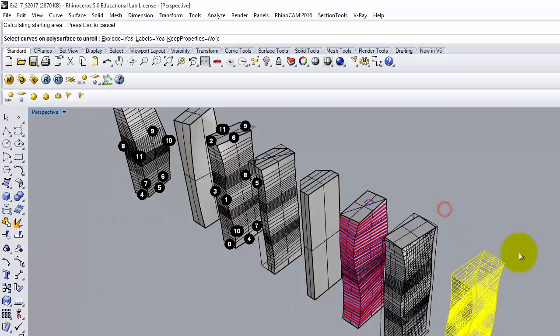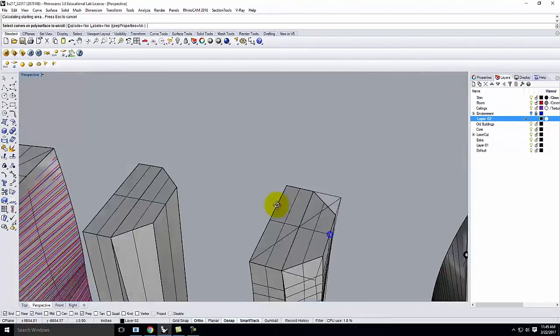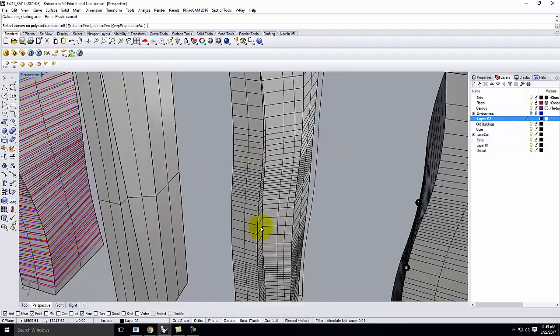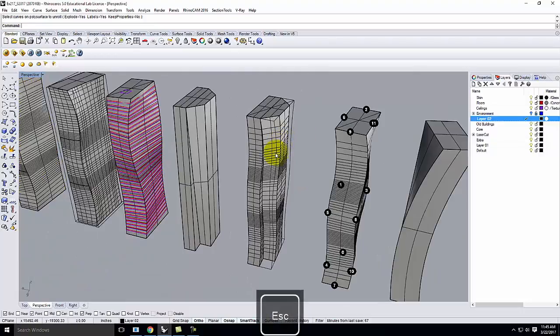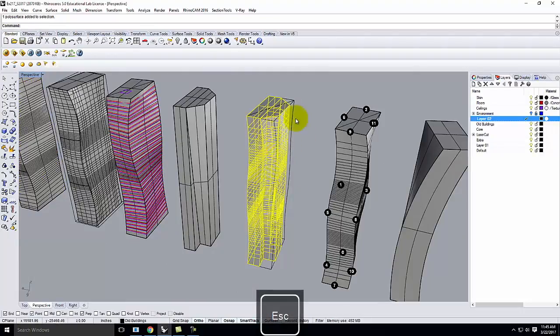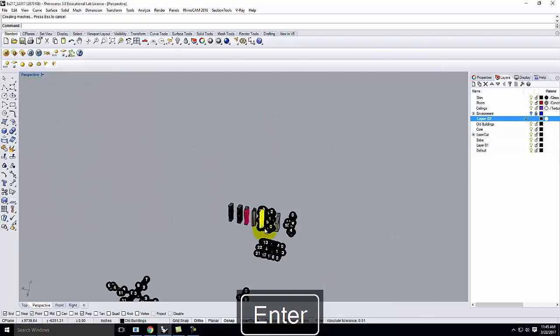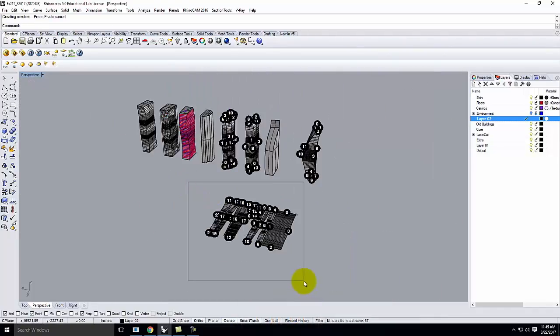So let me do another example over here a little bit. And this one, I have a curve on the building, but I also have a little bit of an inset as part of the building. So if I were to do this, this is a little bit more on the complicated side. It is all lofts. They're all developable surfaces. So if I unroll surface and I get these results, I end up with more pieces, and I have to assemble those pieces together.